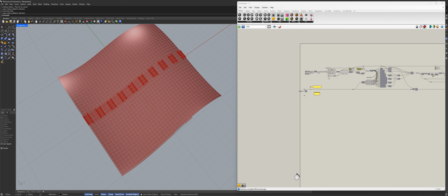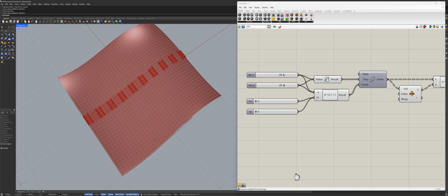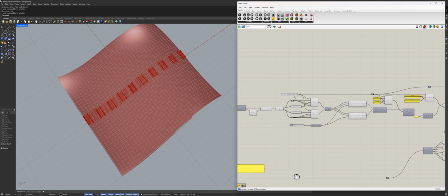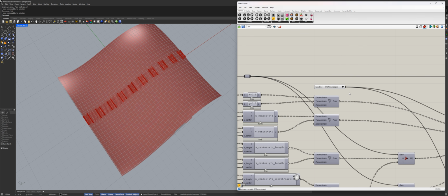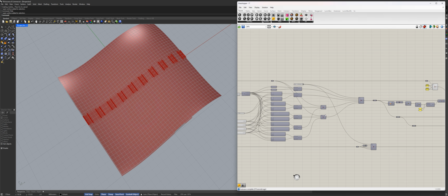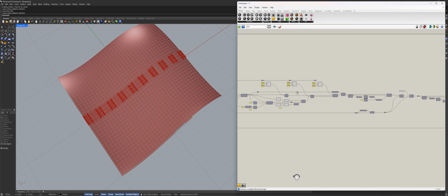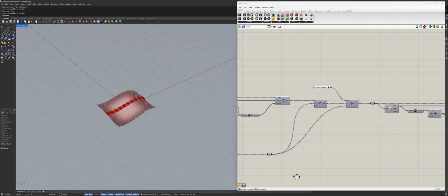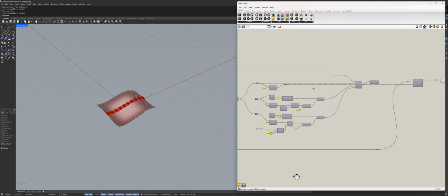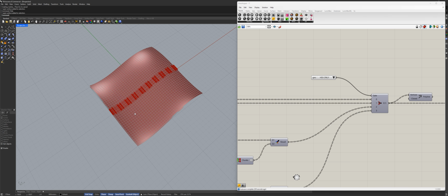Let's look at the parameters, and this is a good thing, so we are on the same page. Our divisions are 28 by 28. We are in the anisotropic flat top orientation, right? We are in a U anisotropic orientation as well, which means that they are working together in the U direction. We are in the open type structure. That's logical, it's not a closed geometry. And we are visualizing only hexes, not triangles, not quads.